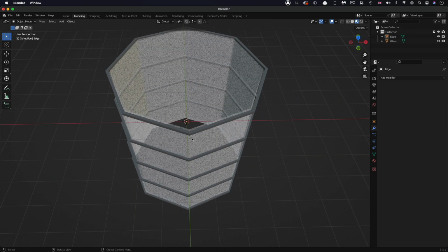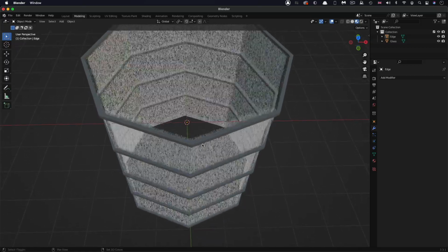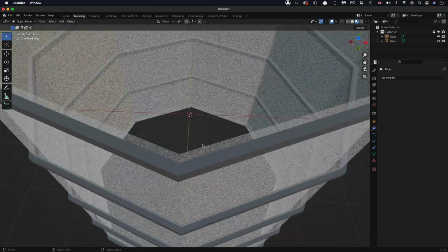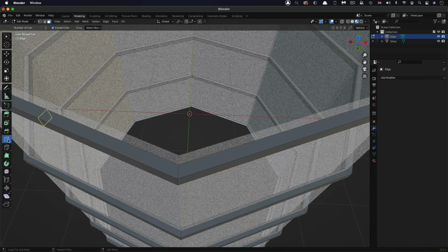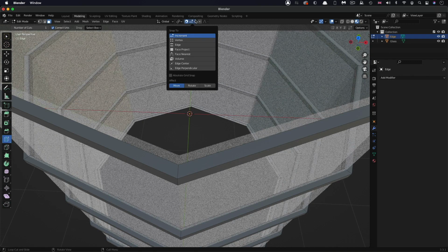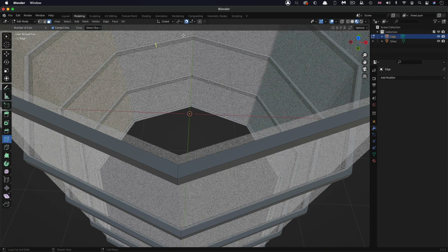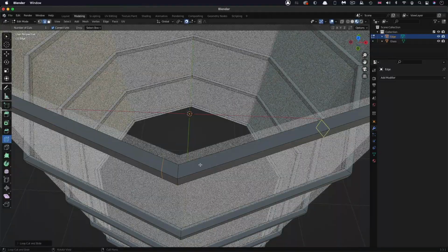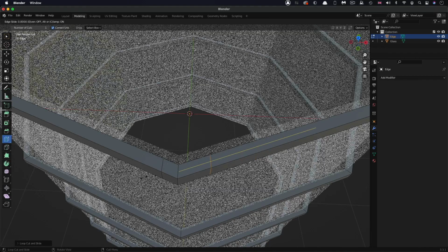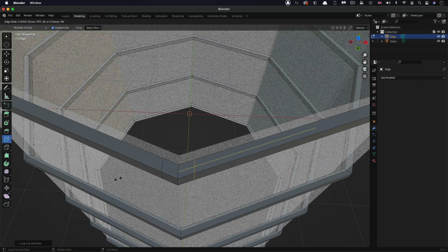So now I want to add the vertical struts, and I could add a 3D cube or something to do this, but what I'm going to do is I'm going to select the edge there, come to edit mode, and come to loop slice, and I'm going to turn on snap, make sure increments is turned on, and then I'm just going to loop slice to there, and on this side, loop slice to there. And because the snap is turned on, those are snapping nicely, symmetrically.